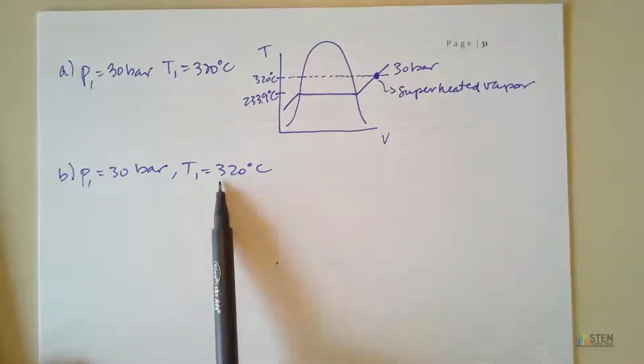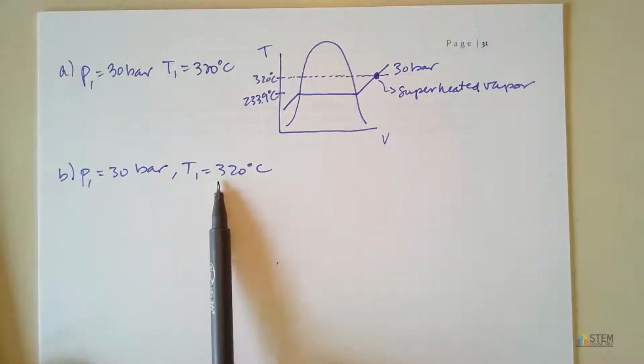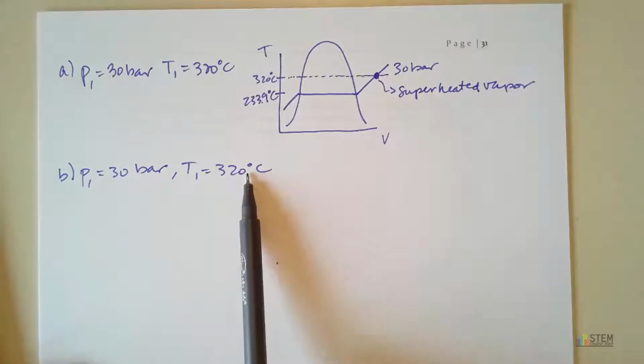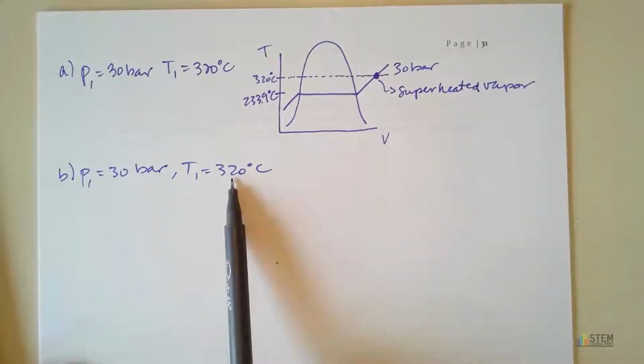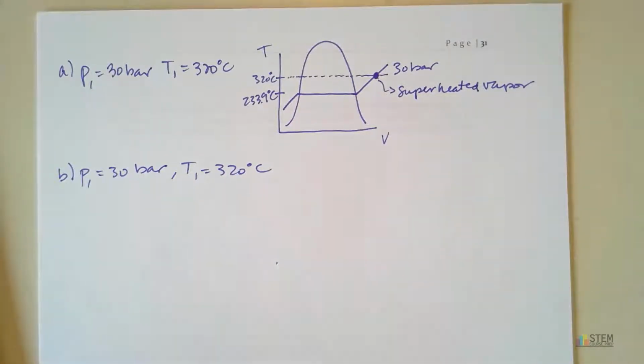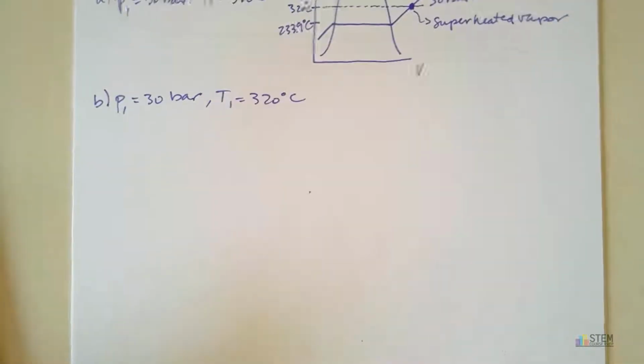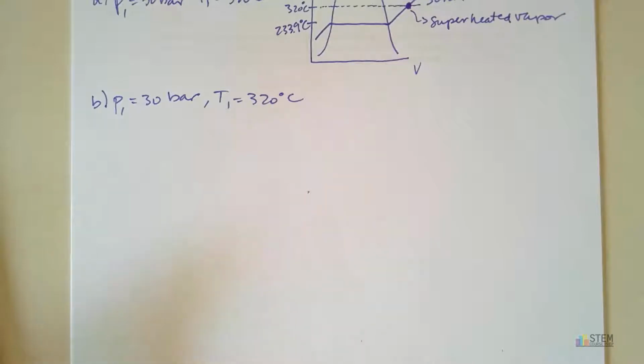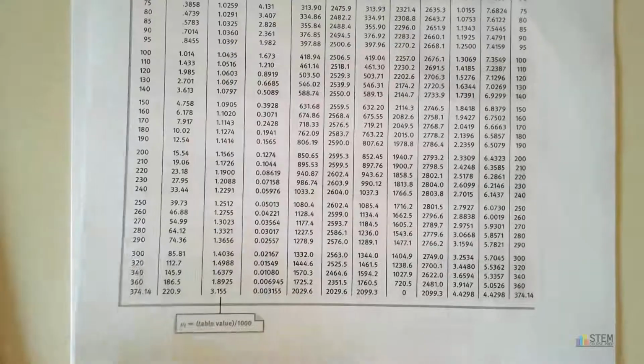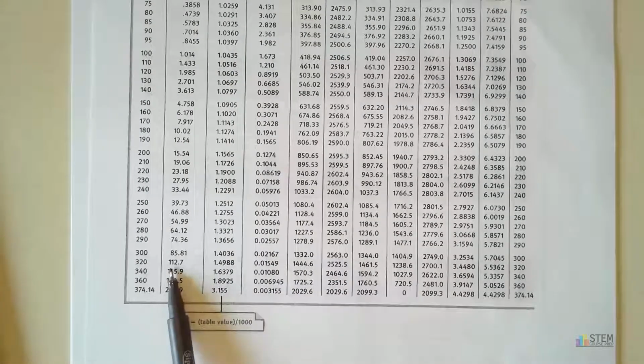So in this case, let's look at the temperature table. So let's take T1, all right, which is 320, and let's find the pressure, so the saturation pressure. So this is going to be table A2 if you're using, sorry about that, the Moran book. And at 320, we have a pressure of 112.7. So this is our saturation pressure. So 112.7.